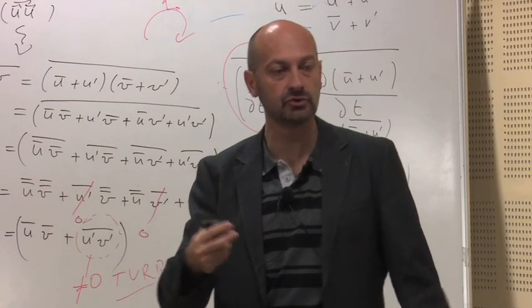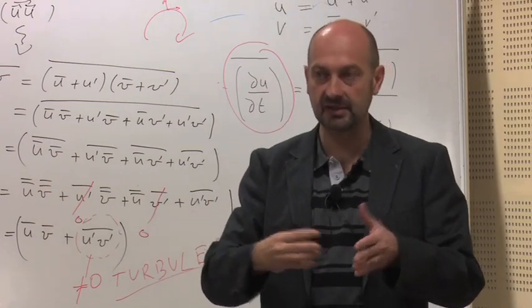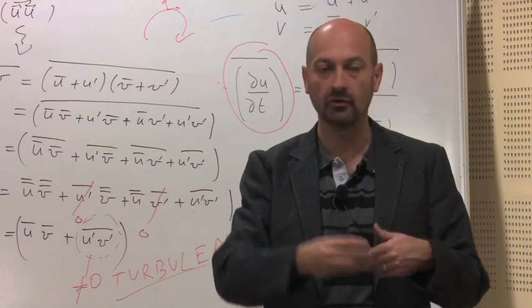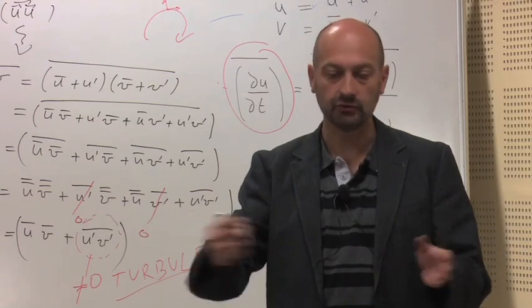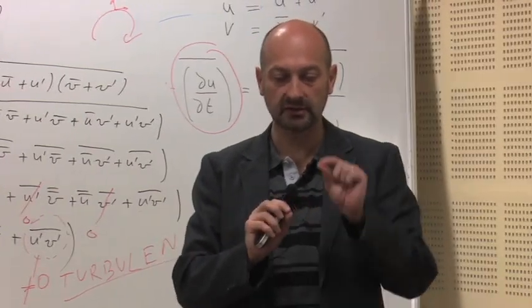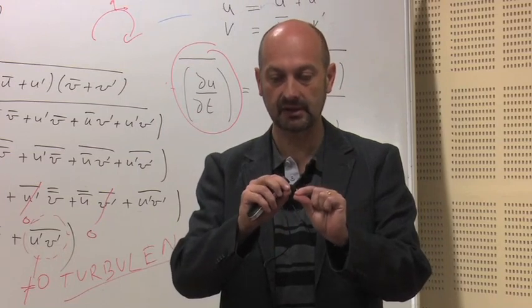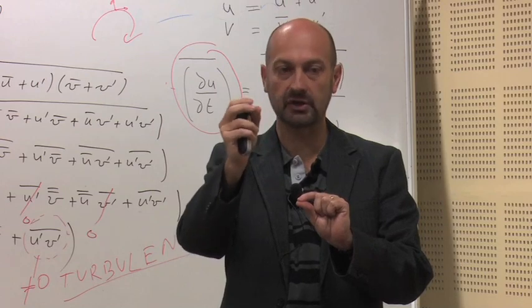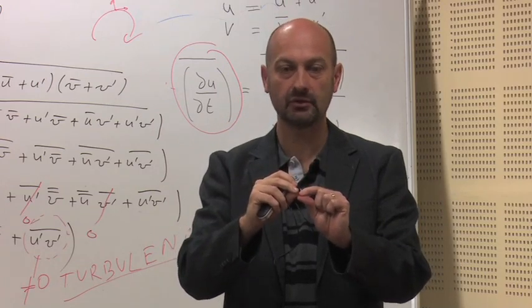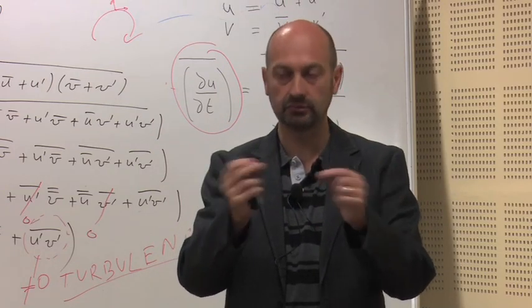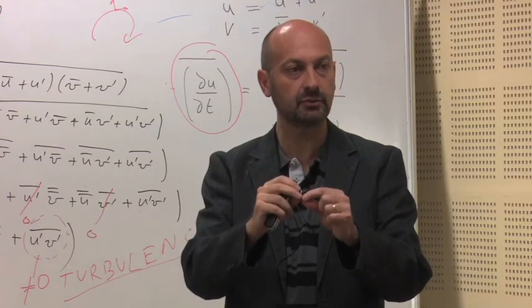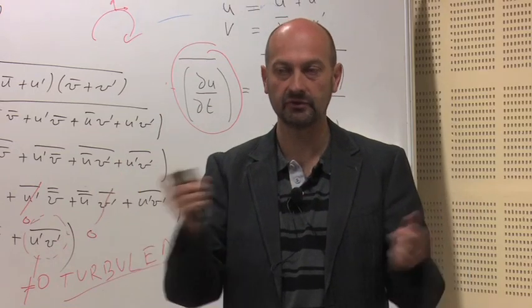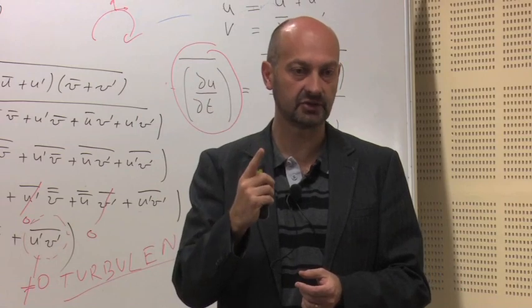And because I want to use this simulation extensively to look at the evolution with velocity, when you change something, you are going to validate one model against another CFD model, which is much more time consuming, but much more accurate, for one operating condition. And then if you are happy, then you are going to use that model for the other operating conditions. So this is one way of validation.